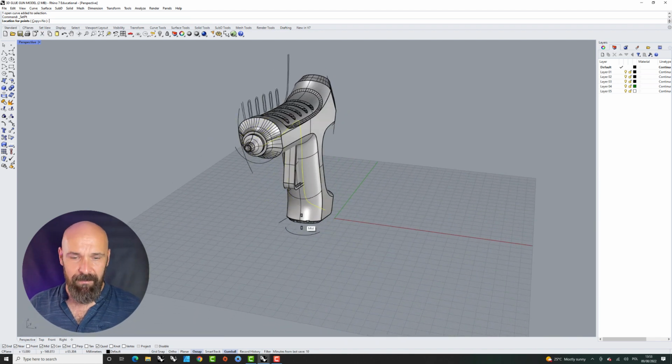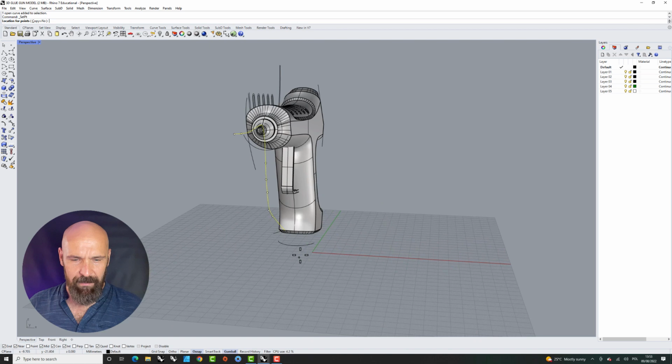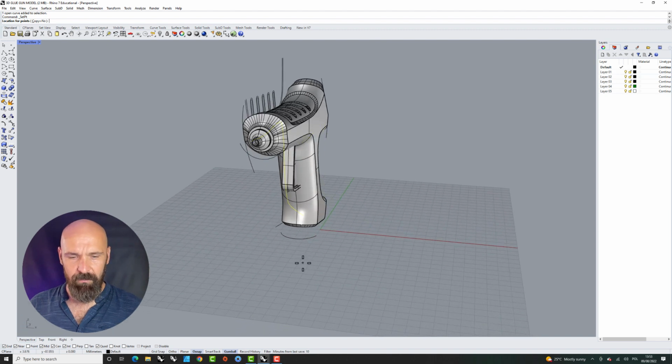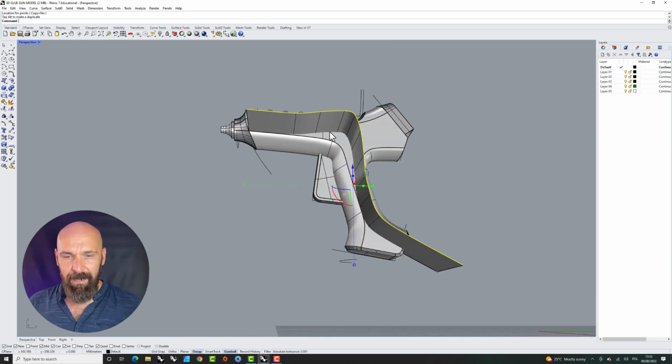In this case, many times I like to place those points at the center of the object, so it's like the middle point, or I type 0 because I'm placing all of my objects at the 0 point, so it depends on you. I'm pretty comfortable with the symmetry of the product I'm designing. And then you can just extrude, or you can cut, trim with that curve, whatever you like. So this helps a lot.